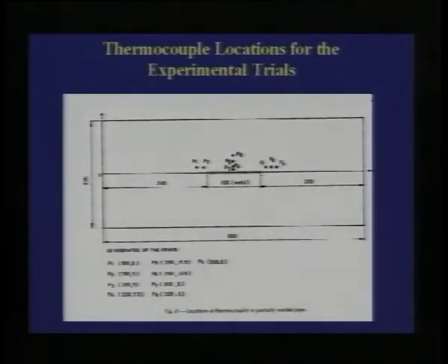Now this is a work which was done in collaboration with an industry, and what is also important is not just to predict temperature. Predicting temperature is important, but also we have to verify it. It is not that every time we run a finite element program you have to verify it, it is not possible, because we are using finite element program for designing. So we may have to run finite element program even before we start manufacturing the product, and hence it is important that at one point of time we verify and see whether whatever results we have or the model we have is correct.